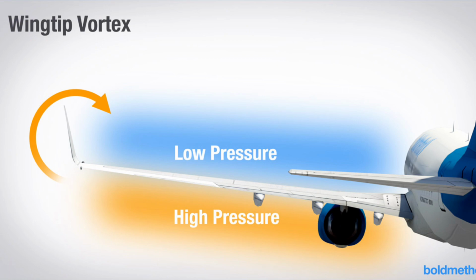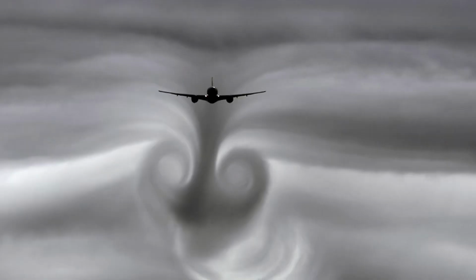The reason why it goes outward is because the air likes to travel with the least resistance, and that is found at the wingtips. The wingtips is where this air will combine from high pressure to low pressure, and thus causing the wingtip vortices. Wingtip vortices are the strongest at high angles of attack, especially when planes are heavy, clean,